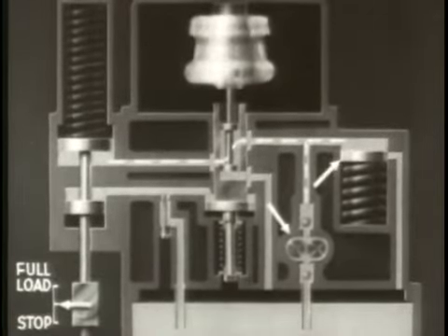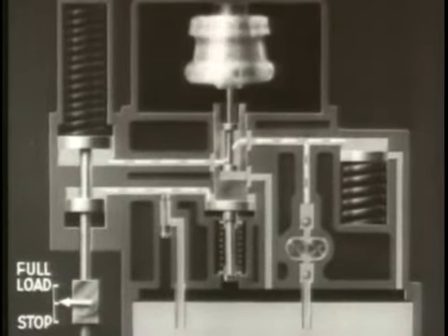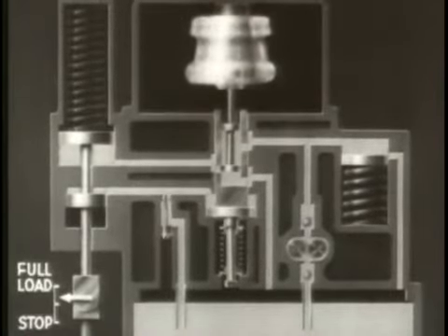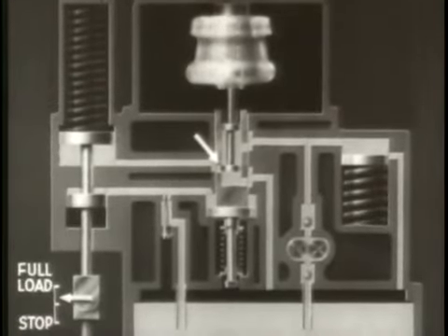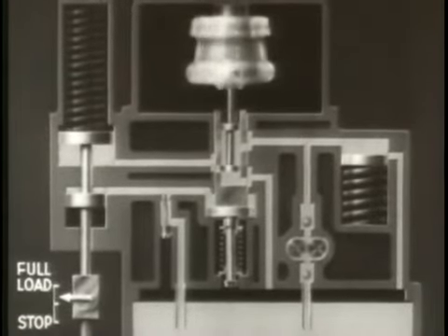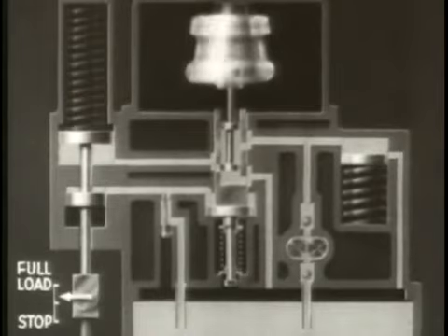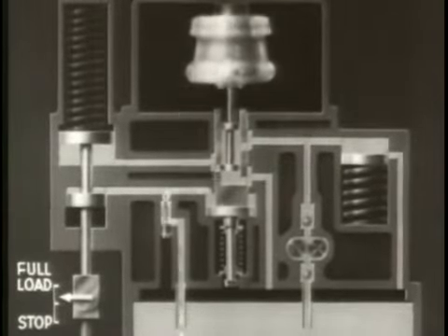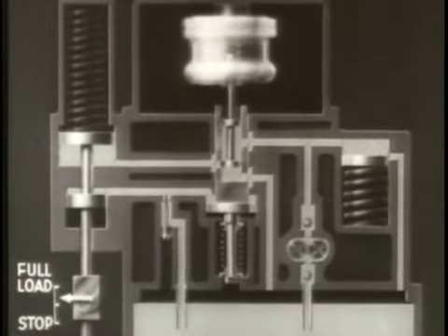Oil from the gear pump and the accumulator forces the power piston upward, increasing the amount of fuel injected into the engine cylinders. In the meantime, the pilot valve bushing has moved downward, closing the port in the pilot valve. As the engine speed returns to normal, the flyweights and the pilot valve plunger and bushing return to their central position.